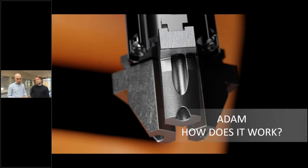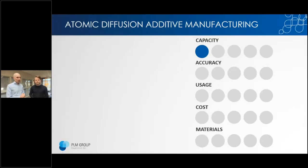So looking into the metrics of this technology, the ADAM technology, it has the lowest capacity, I must say. It has the same speed as an FFF, which is already slow, but then on top of that, you need to sinter and wash the part. So it does have quite a low capacity. Accuracy is also quite low, actually the lowest compared to all the other technologies, because of the same reasons as before.